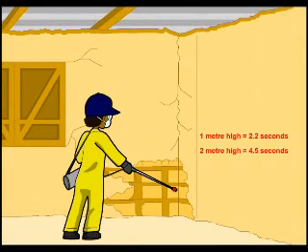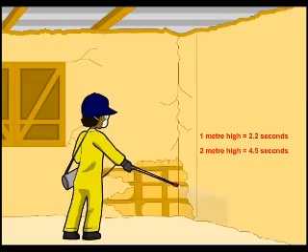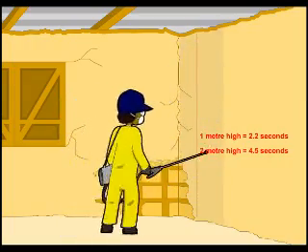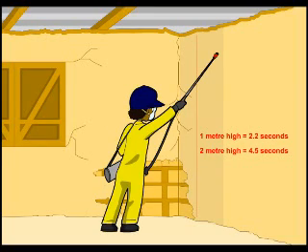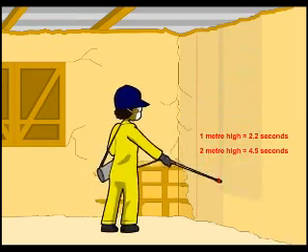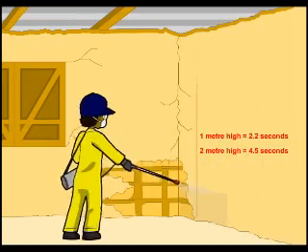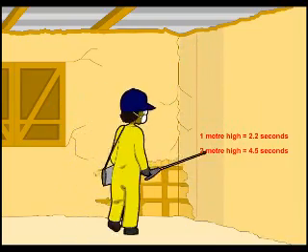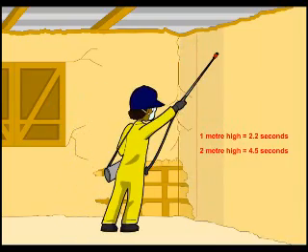Time your spray speed to cover 1 meter every 2.2 seconds. That is 4.5 seconds for a 2-meter high wall. Timing may be aided by mentally counting 1001, 1002, 1003, and so forth. Adjust the mental counting procedure according to the local language.